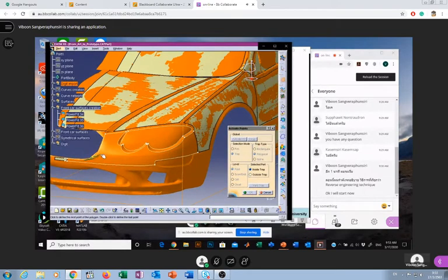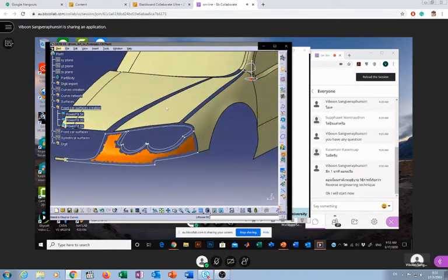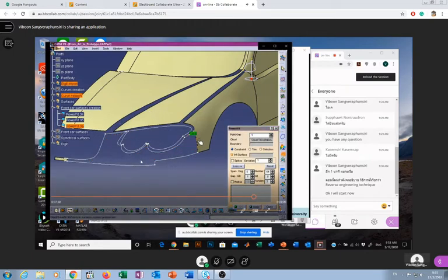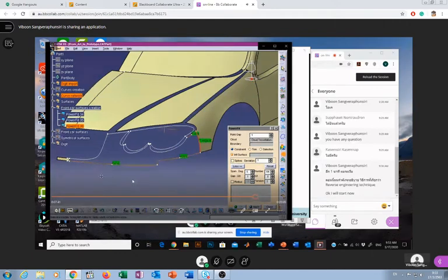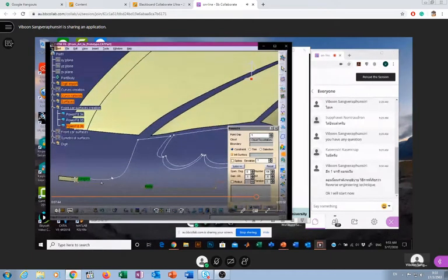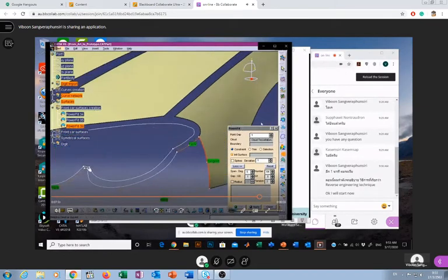You can do the other side as well. You see, we just select points. There are some details if you want to do this digitizing technique that you need to understand. This is just a demonstration of how to do it. You can select points and generate a surface. This is something like a template that you use as a reference and compare to the one that you generate. This one is like a few commands, but inside this module we call it the power fit command.